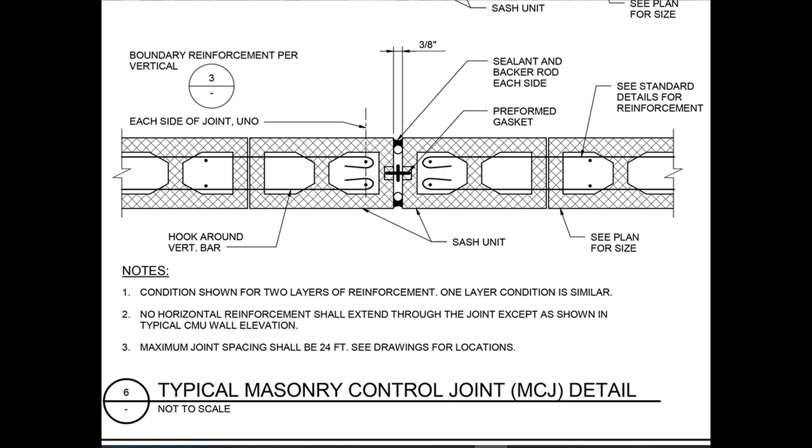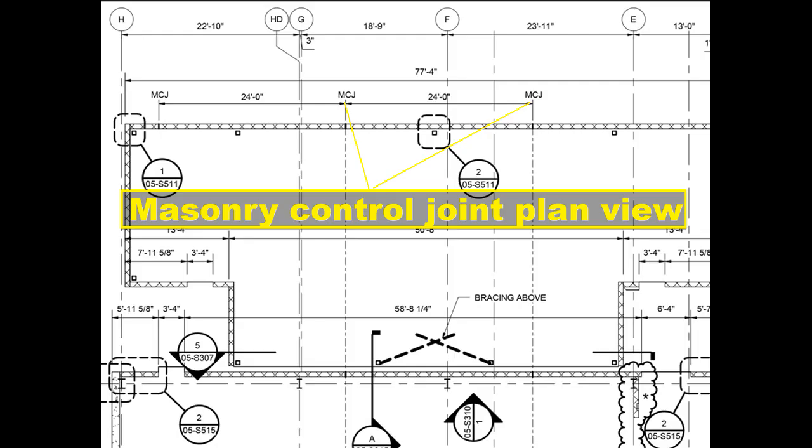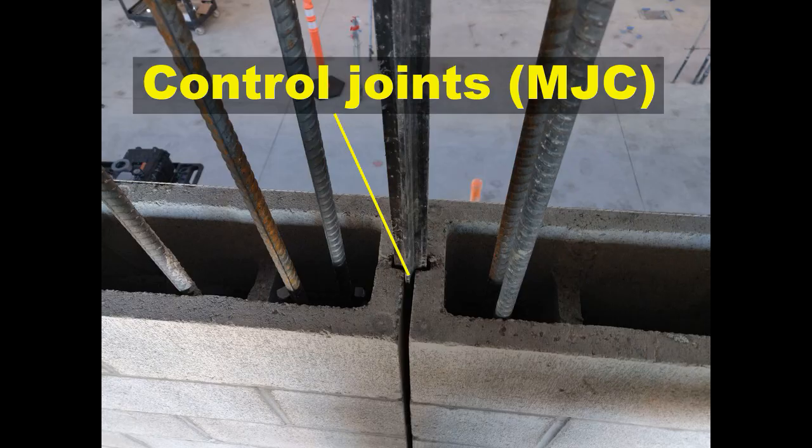Concrete masonry control joint keys. Provide control joint keys of a factory fabricated solid section of natural or synthetic rubber, or combination thereof, conforming to ASTM D2000 with a minimum durometer hardness of 80. Form the control joint key with a solid shear section not less than 5/8 inch thick and 3/8 inch thick flanges, with a tolerance of plus or minus 1/16 inch, to fit neatly, but without forcing, in masonry unit jamb sash grooves.